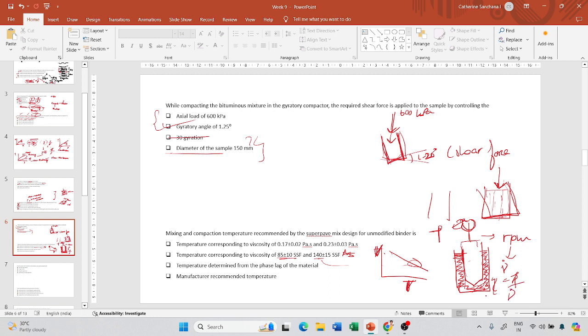Now what they are saying is, you find out the viscosity at different temperatures. They are not mentioning anything about the shear rate. We saw earlier that viscosity depends on shear rate. So if I rotate it at, say, 50 rpm, if my material is non-Newtonian, it is going to have a different viscosity, and if I rotate it at 60 rpm, it is going to have a different viscosity. So they have not mentioned the shear rate, but they have simply said that you just measure the viscosity at different temperatures, and then again you make a plot of viscosity versus temperature.